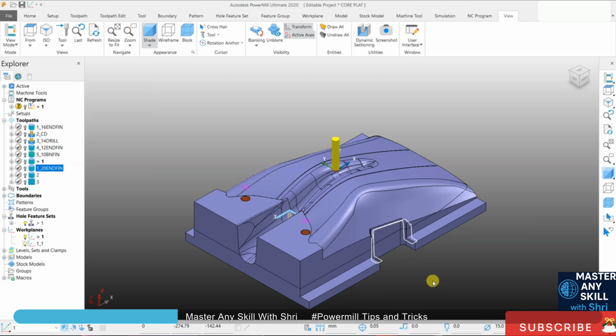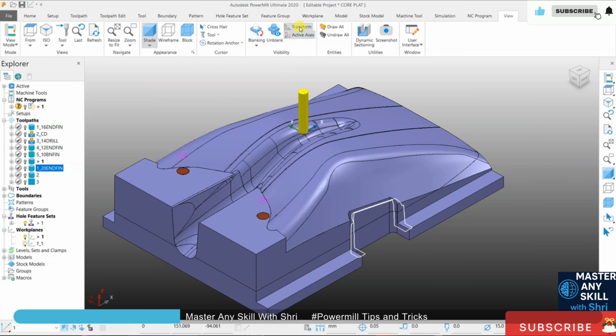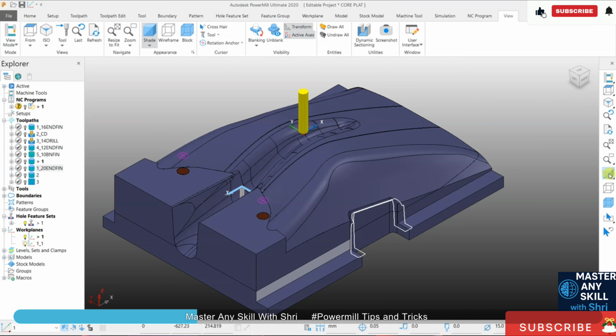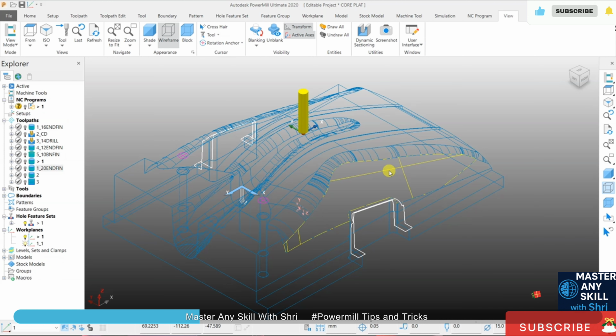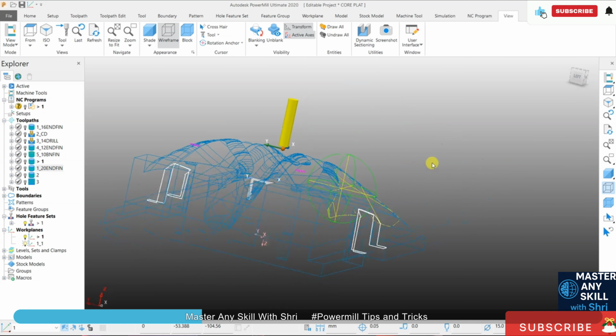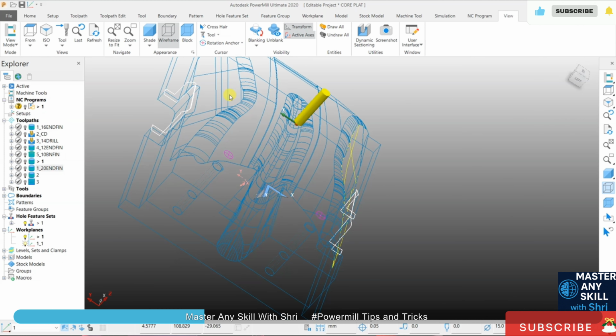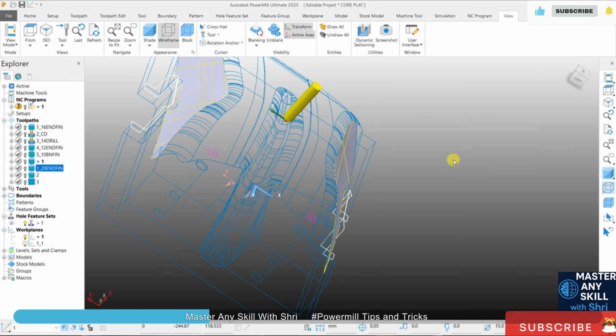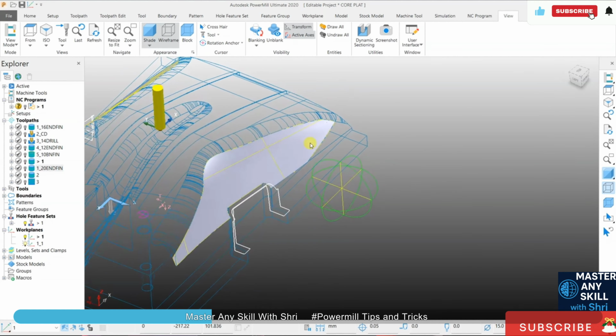And see, here we have this transform option. Click here, and if you don't want this icon, this is a transform, you can hide it. And blank and unblank, we have some shortcuts to blank or unblank. Blank is for hide and unblank is for show. I want to select this curve, so hide this and just show this, and I'm clicking this face, and rotate it, and for this face, use Shift, and both faces are now selected. If you click display, both faces will display.